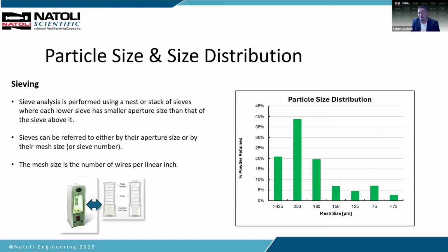Yes, absolutely. Magnesium stearate or stearic acid, sodium stearyl fumarate, those are lubricants we add, and they are fine material, so they're going to be under that 75 micron. Colors, flavors, disintegrants, maybe some binders, they're going to be small, but we want to keep the fines below, I like below 20%. So you can have some fines, but keep it manageable, below, say, 20%.